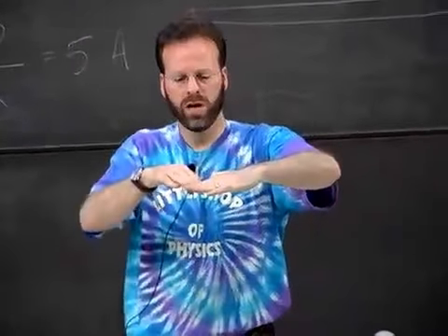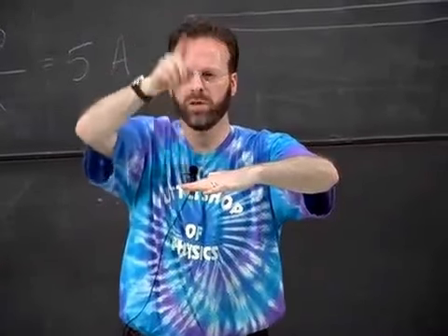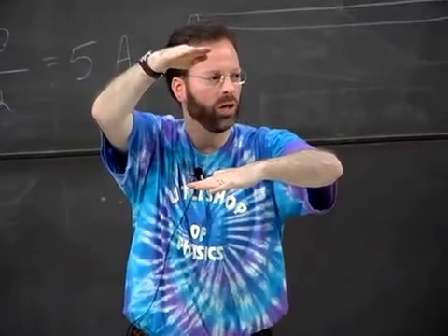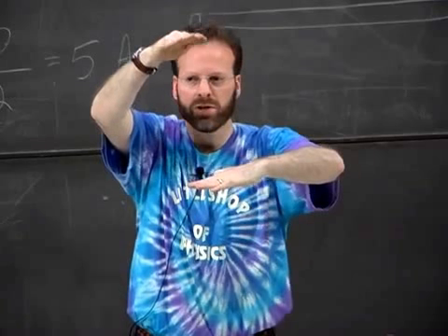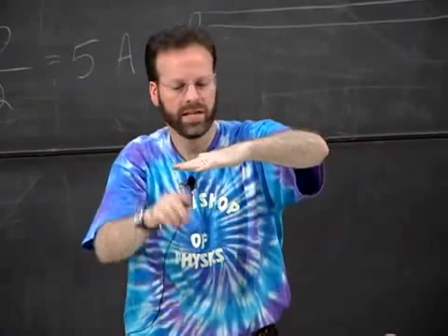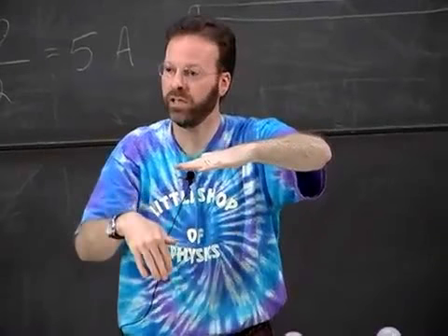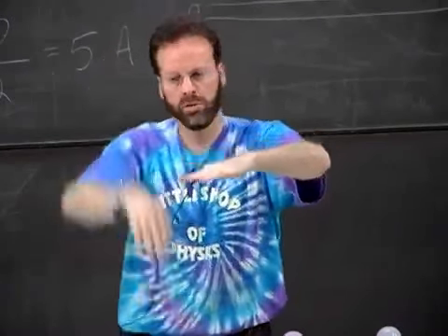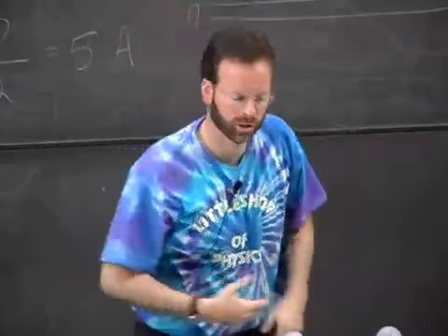So say here's 0 volts. If we rise up to 120 volts, you can set up an electric field and they'll feel a push in one direction. If you want it to go the other way, drop this to negative 120 volts. And that'll set up the electric field oppositely and make the charges go the other way. Then make it positive, then make it negative, then make it positive, then make it negative. That's alternating current.